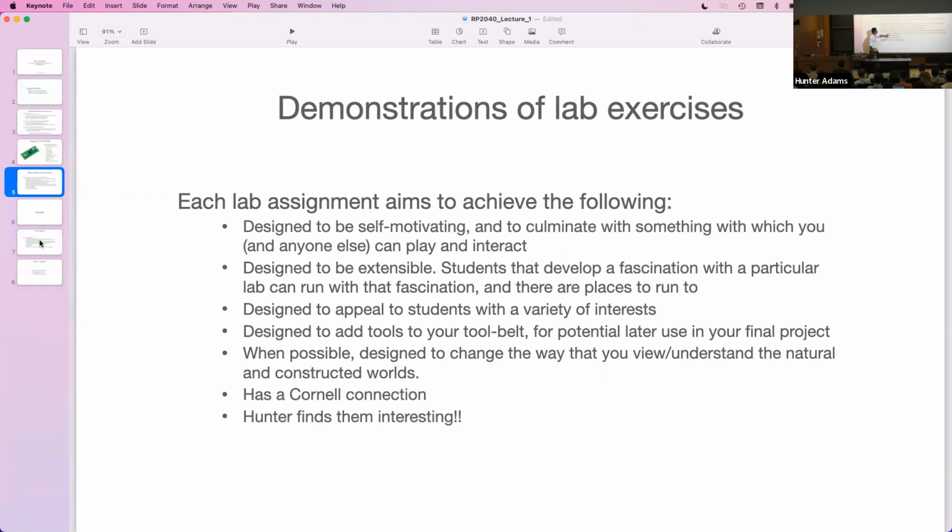The algorithm that we're going to use in this class to synthesize audio is called direct digital synthesis. It allows you to synthesize a target frequency with shocking accuracy, and then you can modulate that frequency. So, you map the frequency sweeps you see in the audio spectrogram to mathematical functions. You implement those to describe the changes in frequency over time, and you can generate simulations of birdsong that are good enough to trick the birds. You can take this system outside and play it, and a bunch of territorial cardinals show up and start yelling at you.